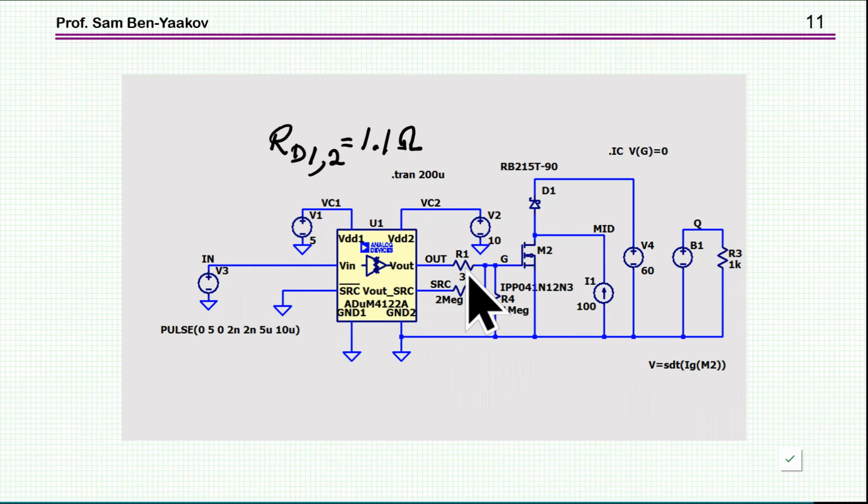And what I have here is the same thing. This is the power supply for this part here. There are 2 transistors here. Actually, it's more than 2 transistors. We'll see it. And here is a 3 ohm resistor. This is the transistor. This is blocked at 2 megaohm, and this is also just a bleeder. I'm also actually not taking it into account. And otherwise, it's the same thing. And I'm also looking at the gate charge, although we have seen it already. So this is a circuit we can actually examine the driver as much as the simulation model is correct.